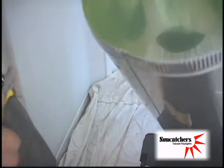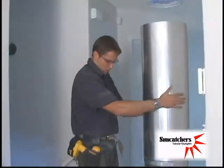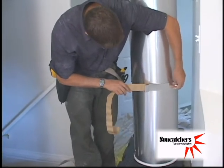Scribe, remove protective film, and tape all other sections of pipe before putting them together with the crimps down. After they're assembled, wrap the joints horizontally with reflective tape.